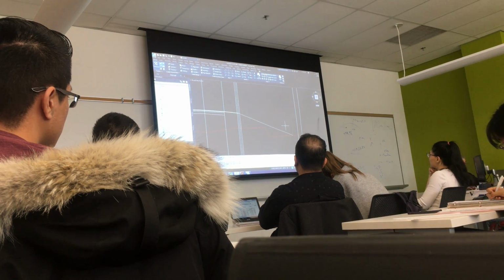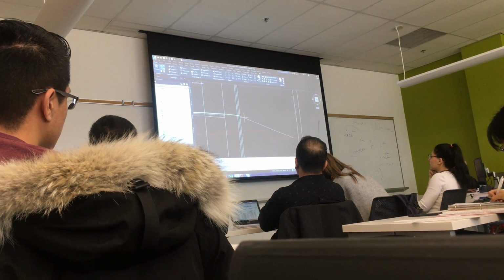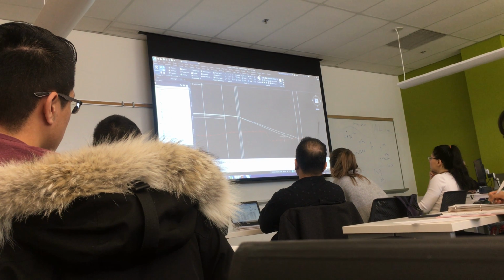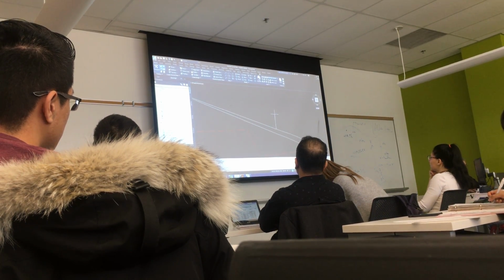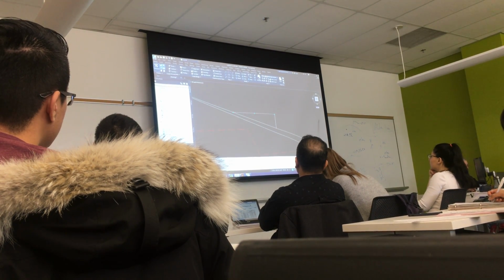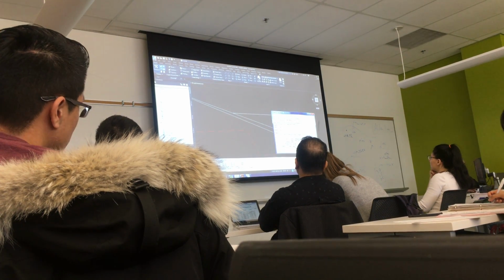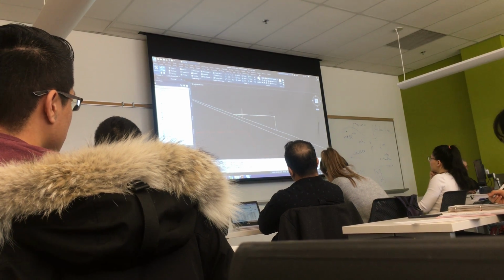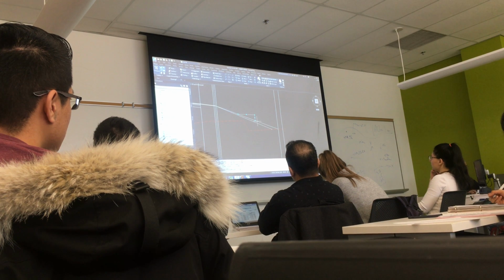If I want to maximize it, I can just draw a line from the roadway all the way to exactly that point. That's going to be flatter than 3 to 1. What's the slope of this line? I'm going to draw a line from here. I'm going to go straight up 1. I'm going to go across, and I'm going to trim it. This length to 1 is the slope of that line, right? It's actually 3.444 to 1. Typically, we use a standard number. Sometimes we use a standard position for where the toe is. It's up to you. I'm going to use 3 to 1.